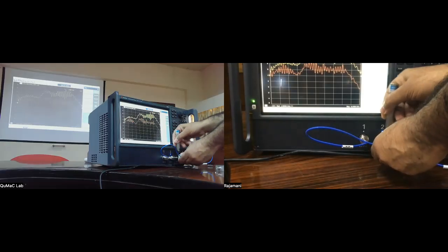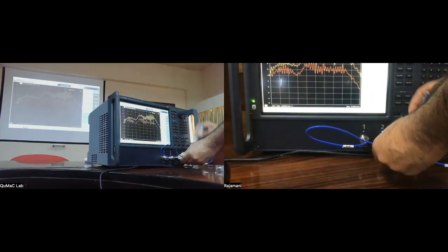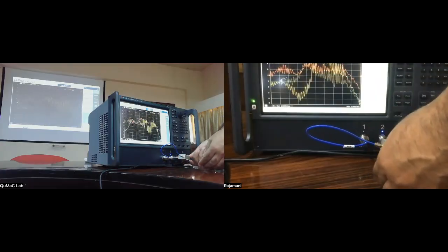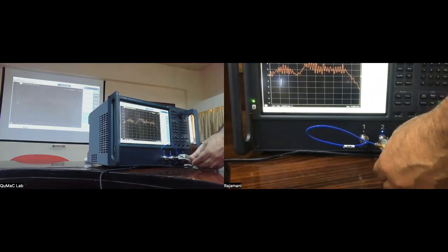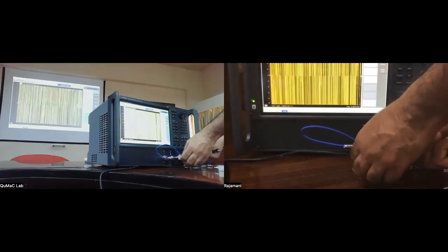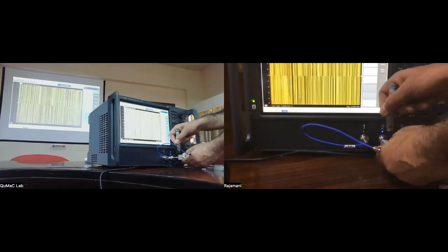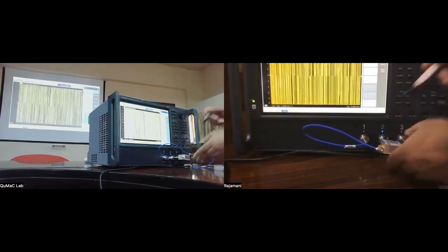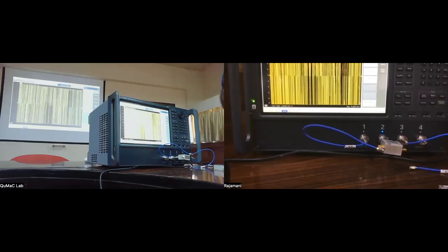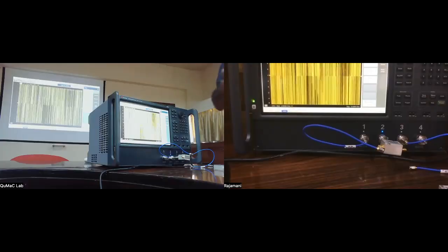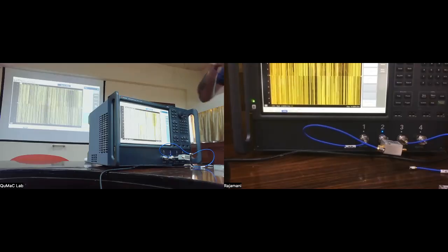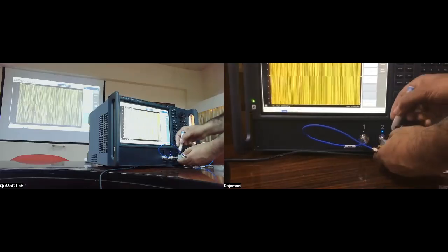This also gives you an idea of typically how accurate microwave devices are when compared to their idealized responses, right? So in Microwave Office, if you make a Wilkinson divider using ideal transmission lines, it will have a very nice looking response. Then if you make it using the pre-solved models, it will have a slightly worse response. Then if you make it with the actual EM structure and solve it, it will have an even worse response. And then in reality, it will be the worst. Okay. So this is actually the truth of microwave devices. It's not a problem, but that's the level at which you can make these things work.